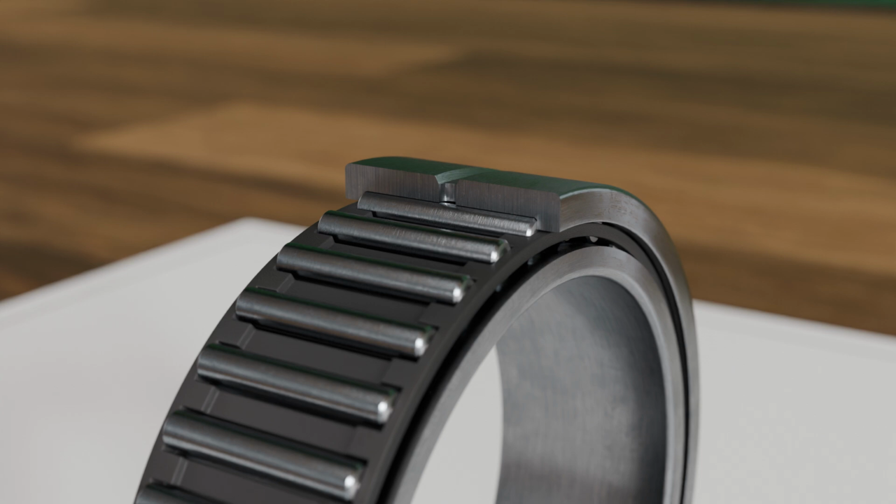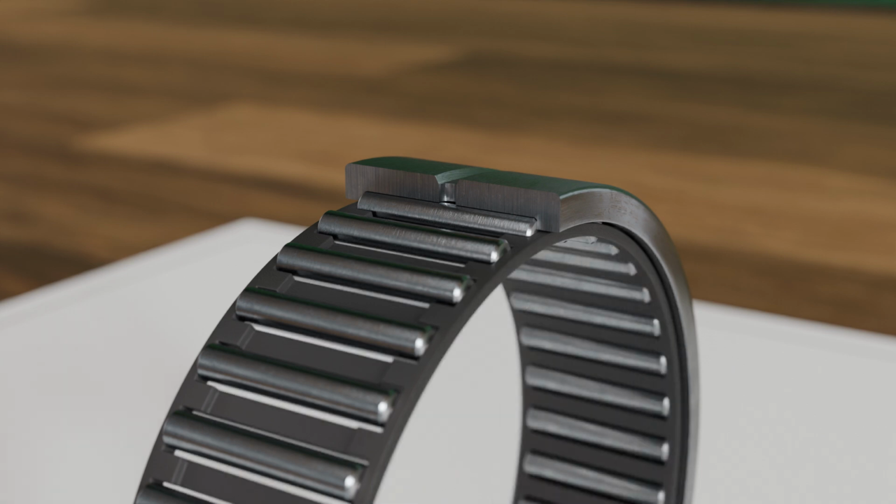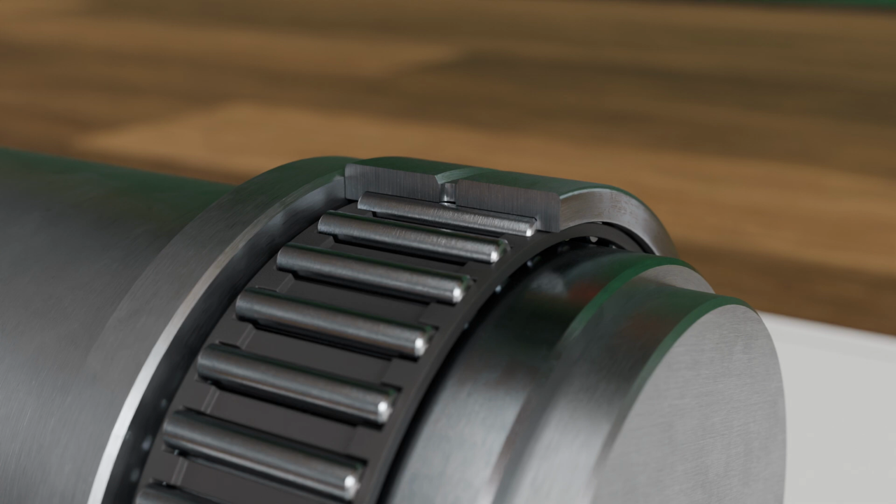The RNA design belongs to the type without an inner ring. It therefore consists only of an outer ring with a needle roller cage and is especially suitable for space-saving designs. A hardened and ground shaft is required, as it serves directly as the raceway. Two fixed flanges on the outer ring provide axial guidance for the needles. A lubrication hole is also present on the outer ring. In addition to these two designs, there are many others which we will not discuss in detail here.